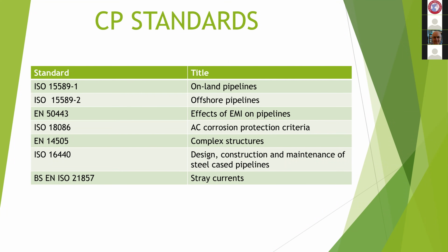We often say you can compare it to the flow of water, which, like all analogies, doesn't hold up for every case. In reality, cathodic protection current and any electric current will take every possible path available to it. It's just that for the very high resistance parts, the amount of current that arrives is negligible. So if you connect two things together, like a pipeline and a very low resistance earth, the majority of the current is going to go to the earth and not to your structure.